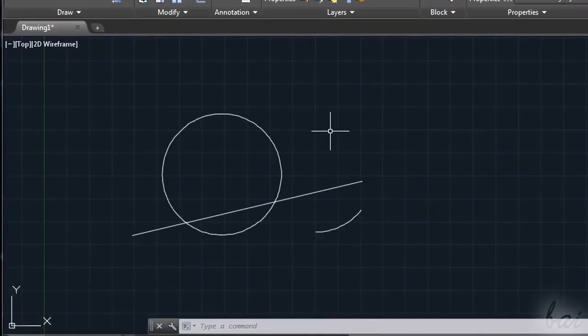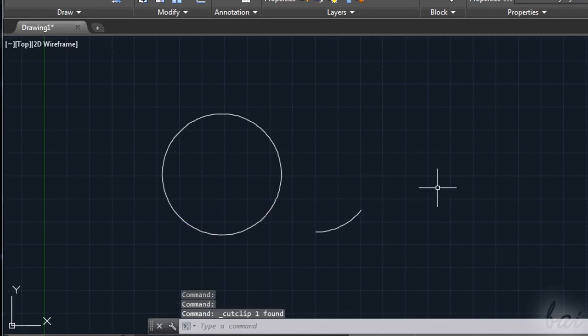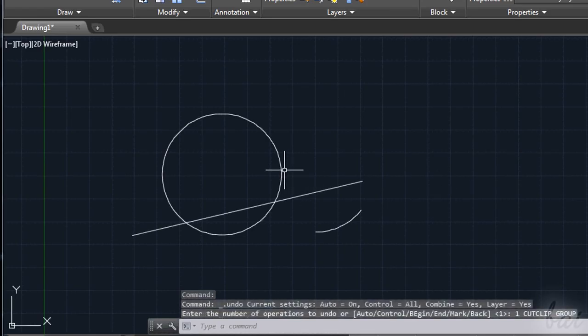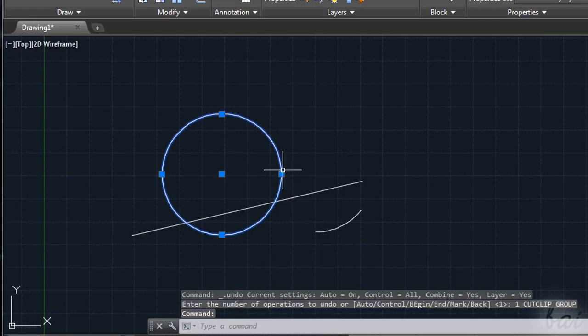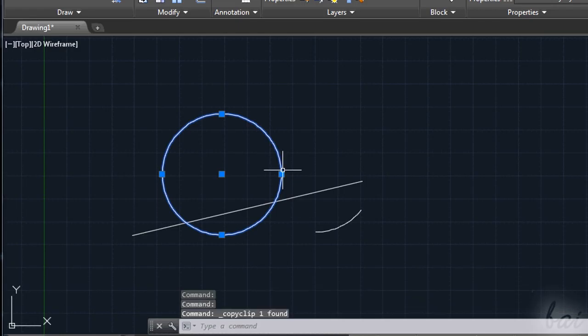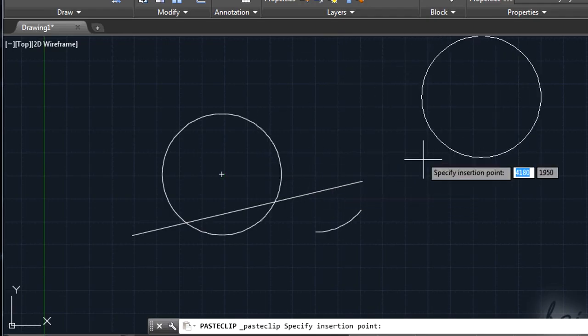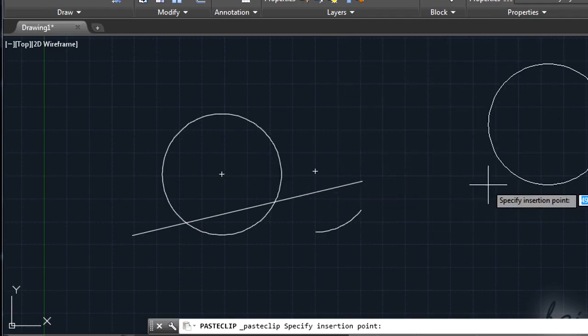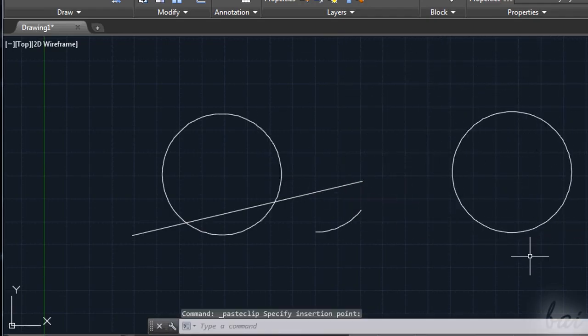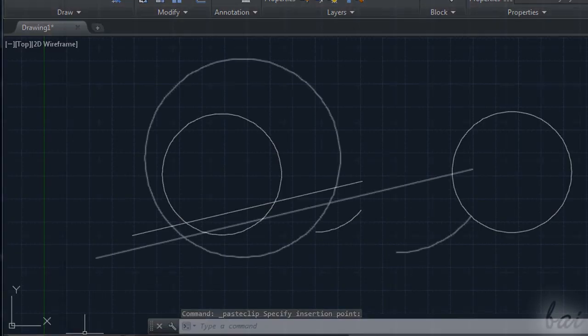If you drew objects wrongly, you can delete them fast. Just click on them and press Ctrl and X to cut them. So you can use Ctrl and C and Ctrl and V to copy and paste objects fast in this way. When you paste, a preview is shown to make you see where you are placing the object.